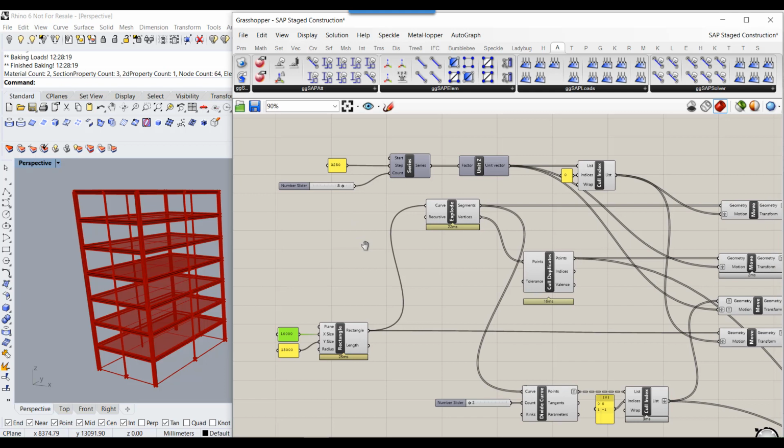Typically for a building you might have special construction loading, or you might have a temporary stage where the slab may not be poured, and you might be relying on that slab for beam strength, and you'll need to employ temporary props over a certain number of levels. So that's what we're going to try and replicate here today.